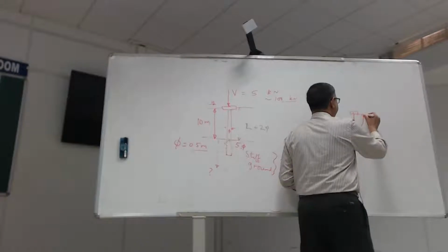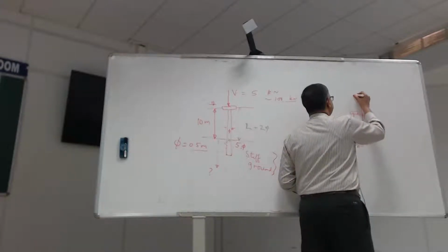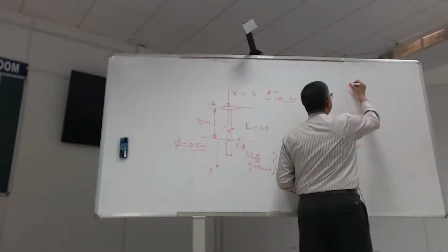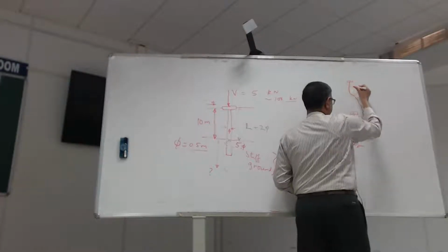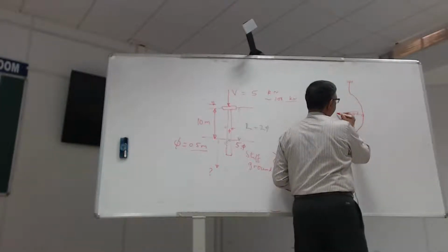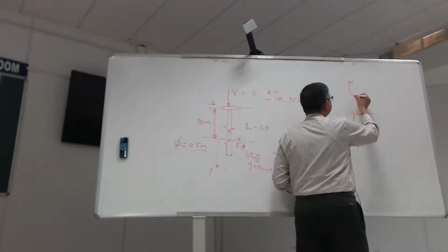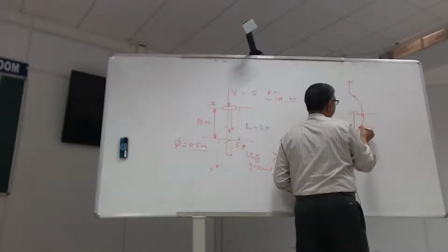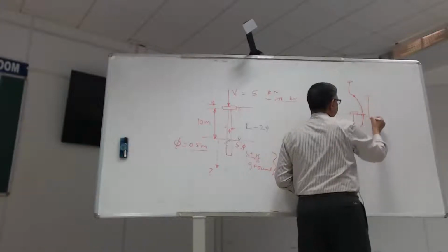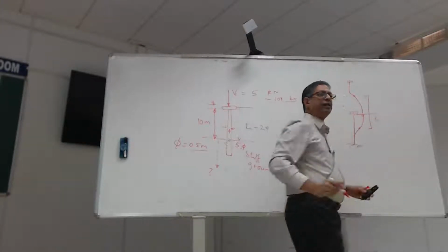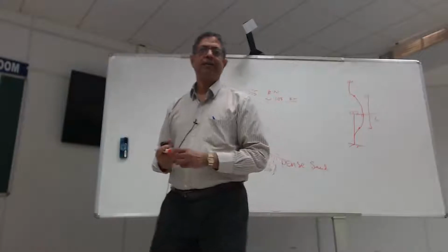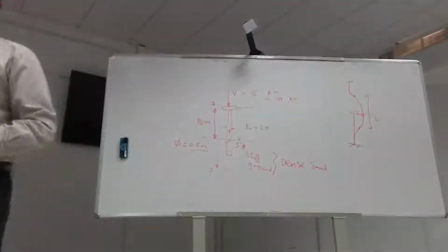If I continue this, reflect this onto the top, it should be symmetric about that axis, and you measure the distance between the points of contraflexure, and that turns out to be L. So this is how you do it using mode shapes.